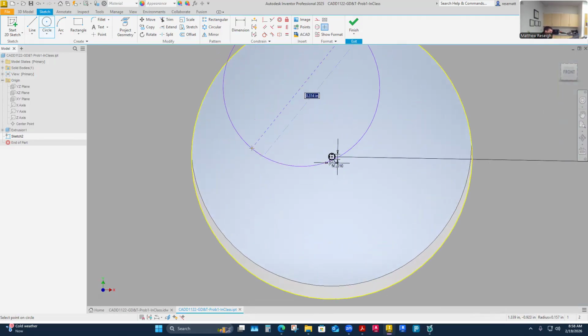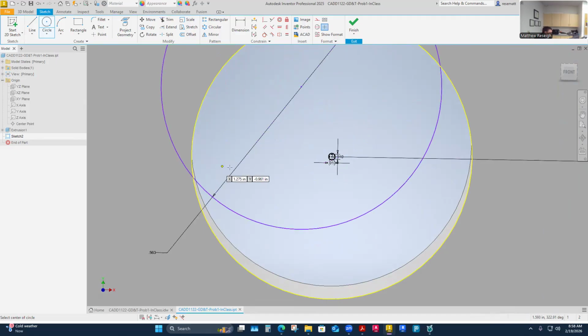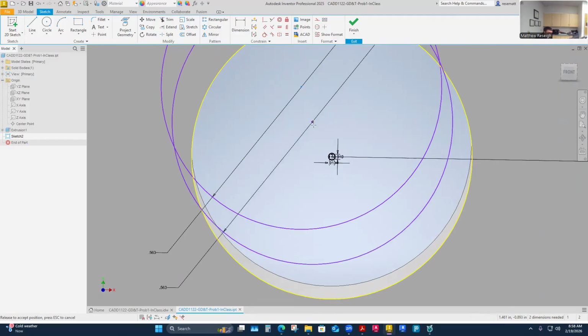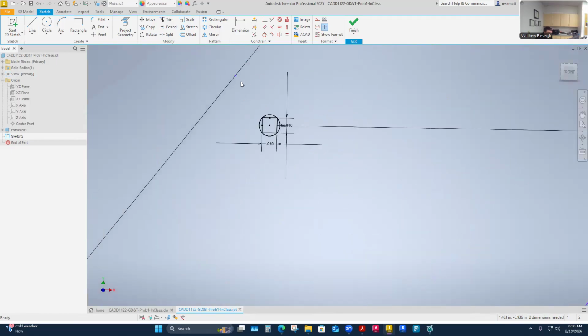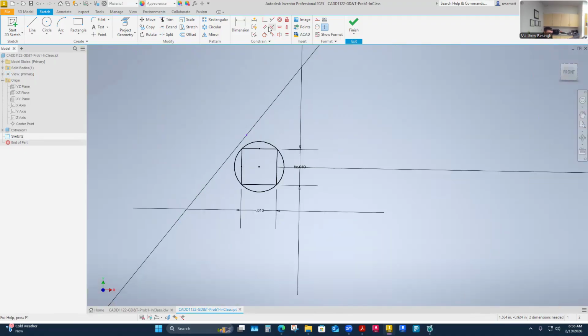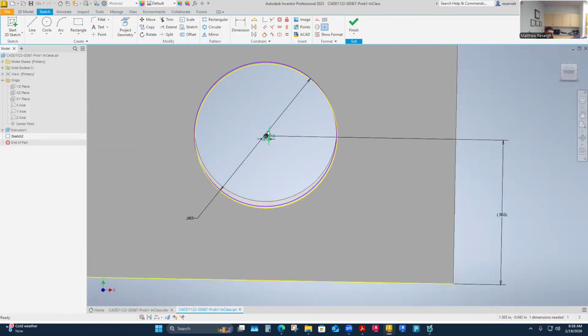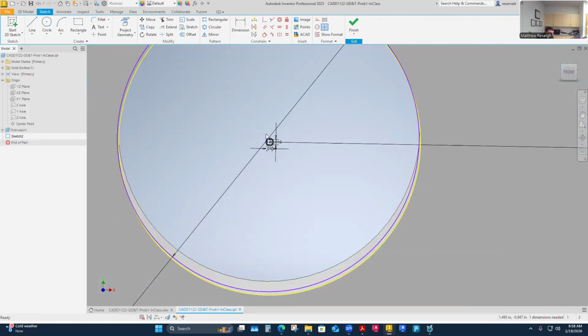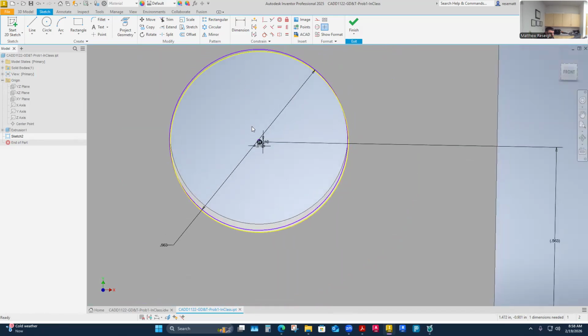Because here's my point: this is the .5625 dimensioned circle. If I snap it to this circle, I'll just do a coincident constraint, this to this. And now this is how much sloppier my whole location can get if I move out and roll it around this radius. This is really where I am now with positional tolerance.